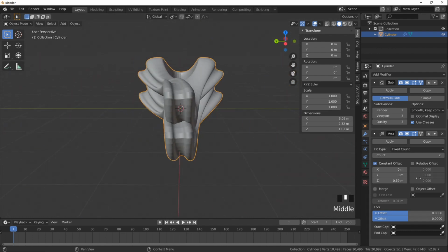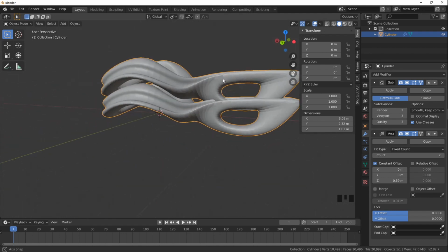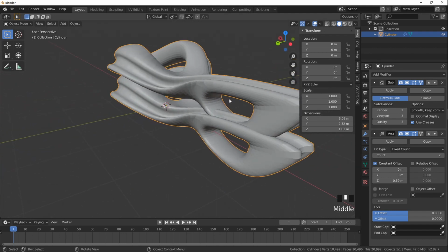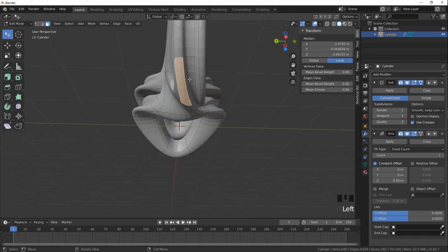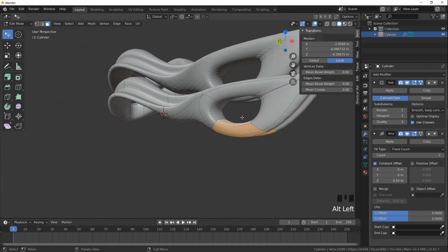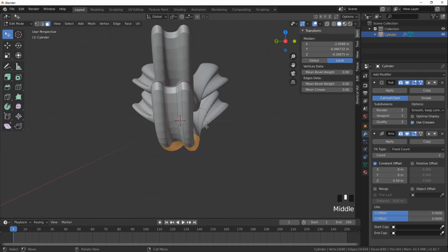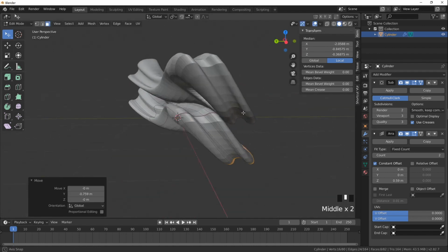The difference is that this one is proportional to the size of the object, this one represents the distance between the two objects. Now we of course have some intersections here, but in edit mode we can edit this object here, selecting those faces. Actually we can select the entire loop and moving on one side. So you see that they are avoiding each other.